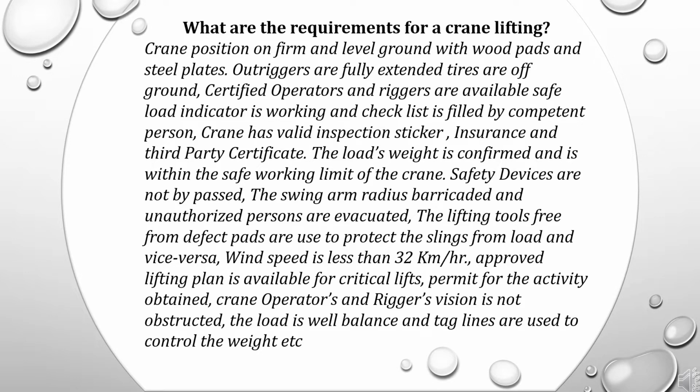What are the requirements for a crane lifting? Crane position on firm and level ground with wood pads and steel plates. Outriggers are fully extended, tires are off ground, certified operators and riggers are available, safe load indicator is working and checklist is filled by competent person, crane has valid inspection sticker, insurance and third-party certificate. The load's weight is confirmed and is within the safe working limit of the crane.